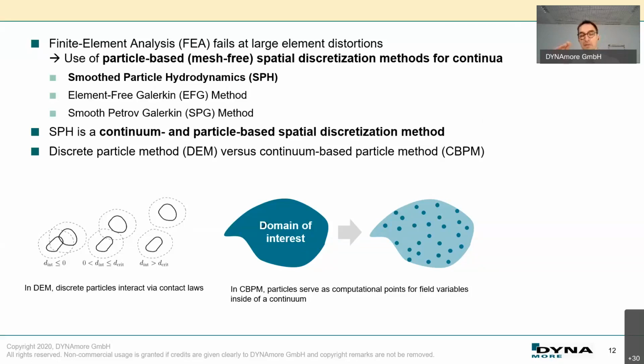And please don't confuse this with real discrete element or real particle methods. So if I compare this one, this is a particle method. In a particle method, you have indivisible particles following the momentum balance, but the particles interact through contact. You have a Hertzian contact, particles bouncing off each other, bouncing back again. That's how they interact.